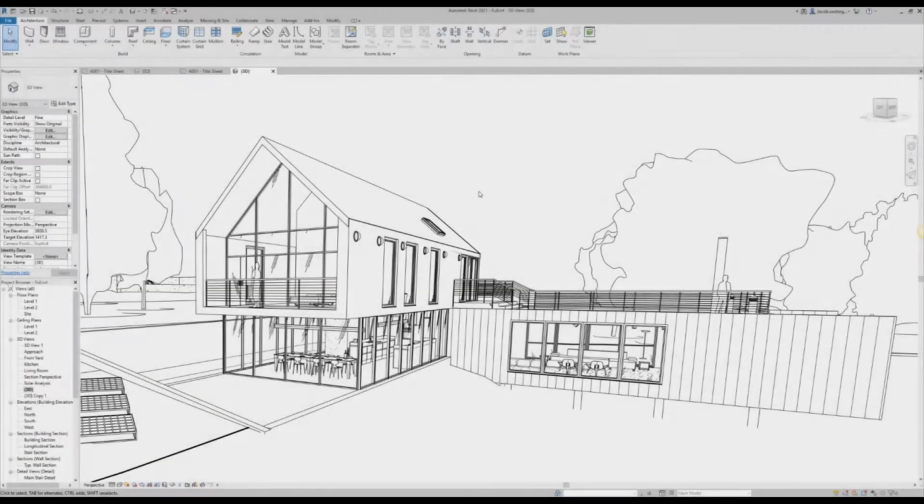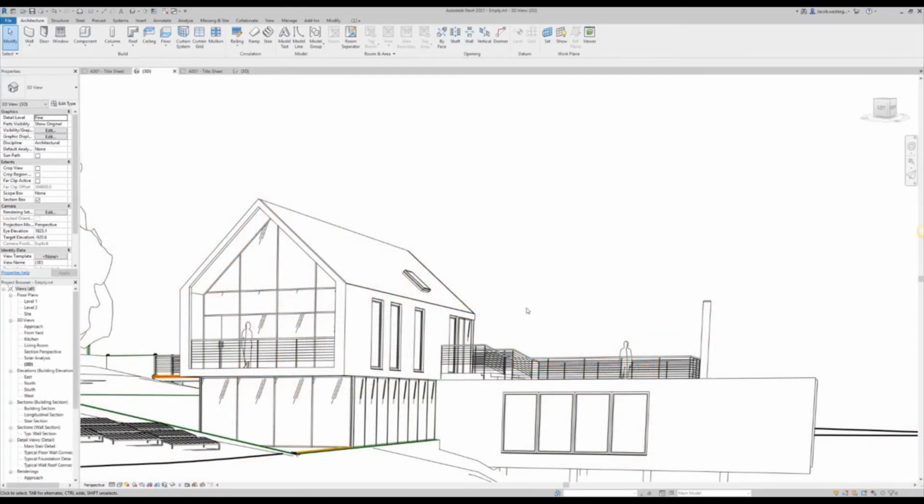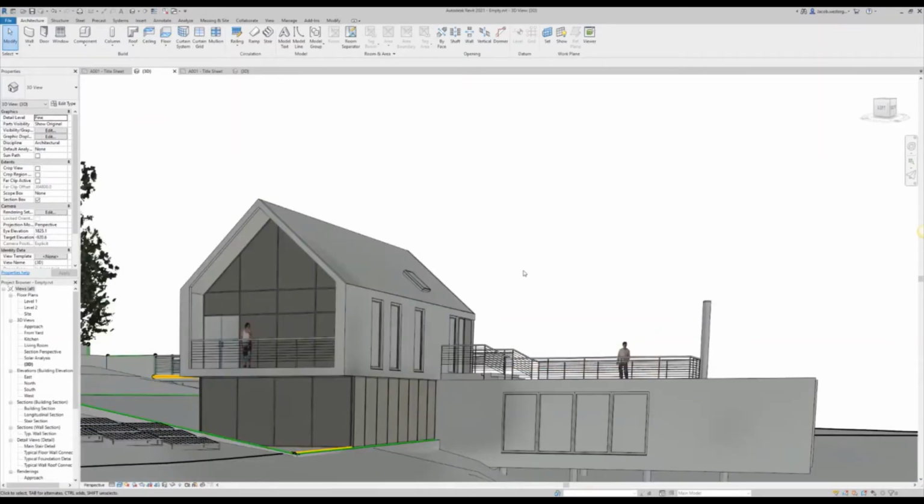To enable realistic view, you go down to the bottom left and you change it to realistic. Changing between the visual styles is straightforward, but to get a good visual from the realistic view, you have to apply the right materials and configure them so they fit with the surfaces they apply to. If there's no material applied, you will end up with a gray surface as shown here.